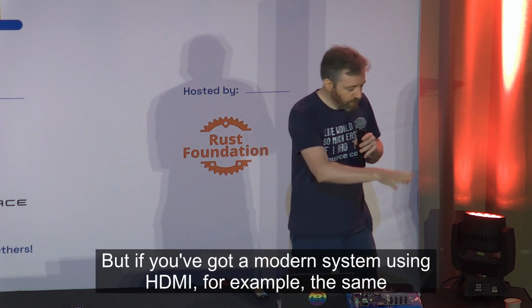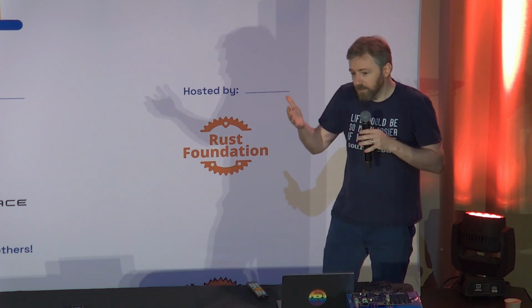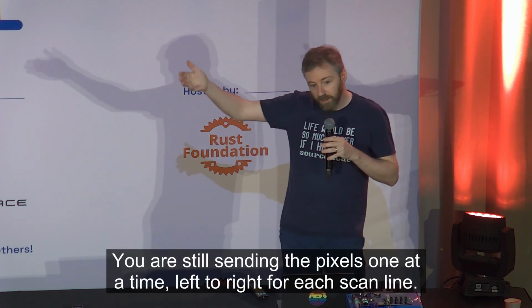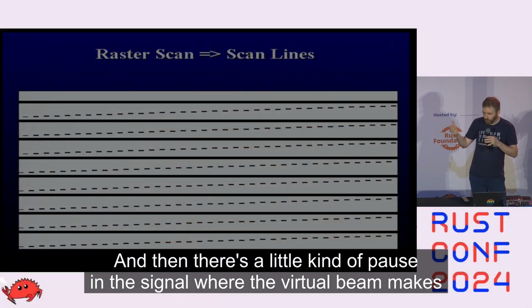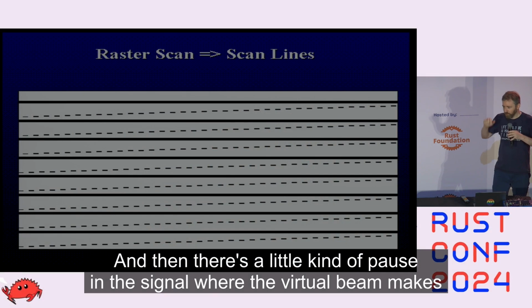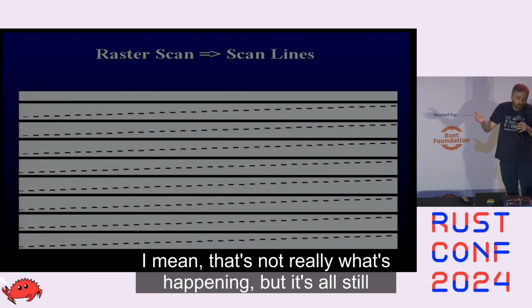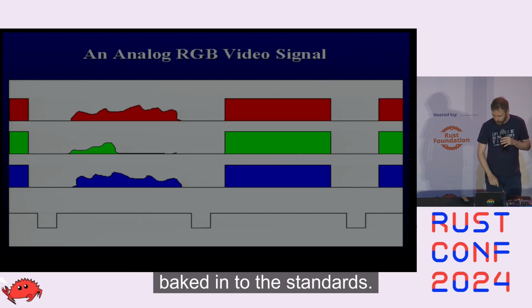But if you've got a modern system using HDMI, for example, the same kind of thing still happens. You are still sending the pixels one at a time, left to right for each scan line, and then there's a little kind of pause in the signal where the virtual beam makes its way back to the virtual left-hand side of the screen. I mean, that's not really what's happening, but it's all still baked in to the standards.